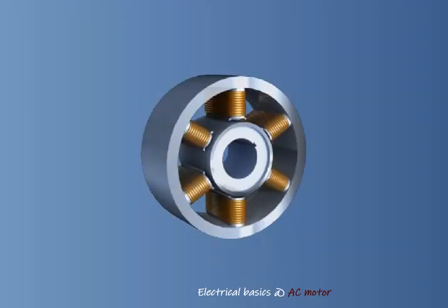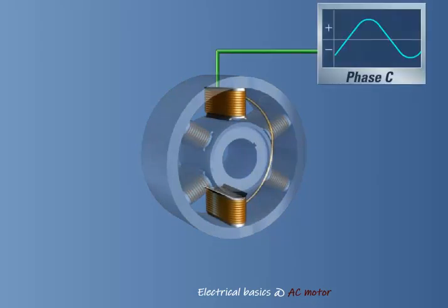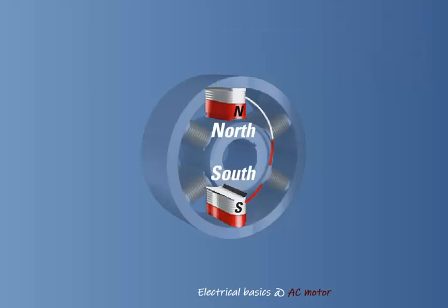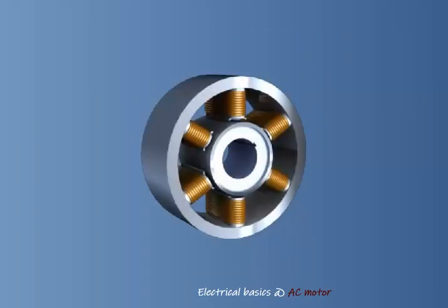The electromagnets in each phase of this 2-pole motor are wired such that when current flows through one pole or electromagnet, it flows in the opposite direction through the second electromagnet or pole. For each phase, the resulting magnetic fields, and hence poles, facing the center of the motor are reversed as illustrated. We have labeled the electromagnets or poles in each phase as shown.